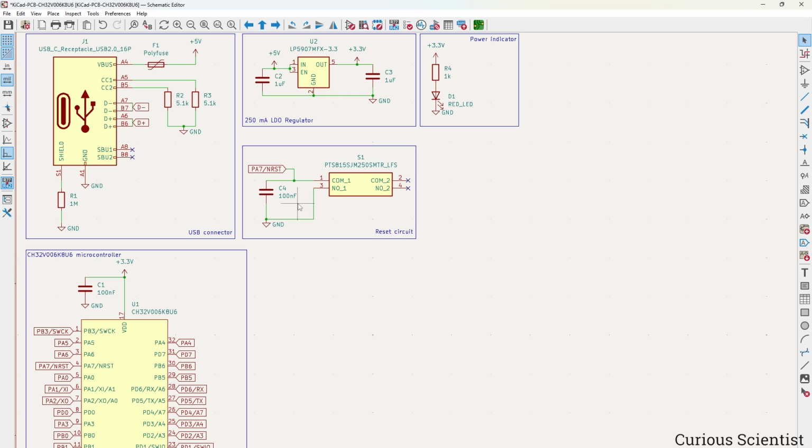So now what we have here is that based on the datasheet's recommendation, we have the capacitor, and at one of the pins, the reset pin is connected. So that's nice. And when the button is pressed, internally the COM1 is connected to NO1 here. So therefore the reset pin will be pulled to ground. So it's that simple. Then the next step is the oscillator.